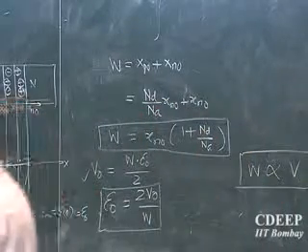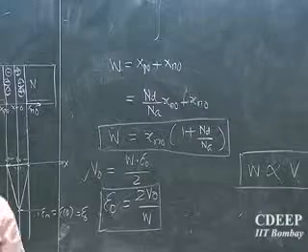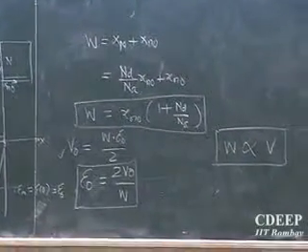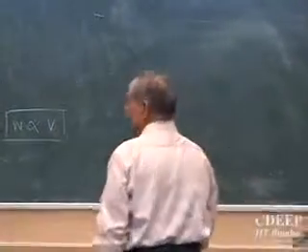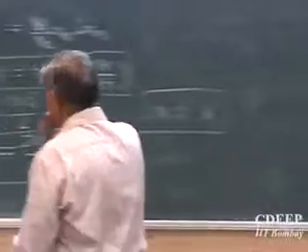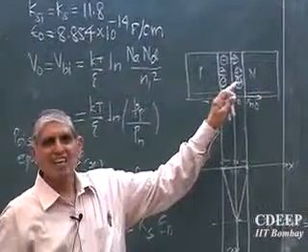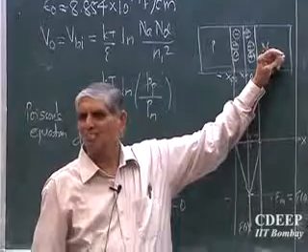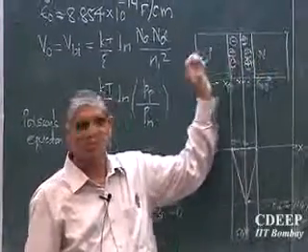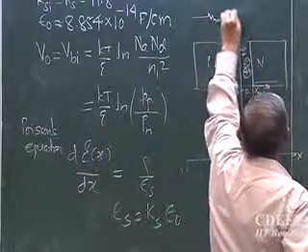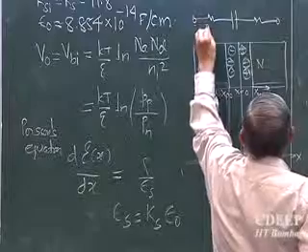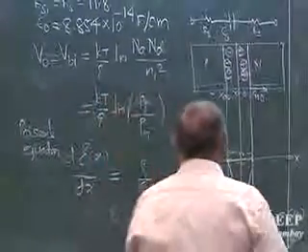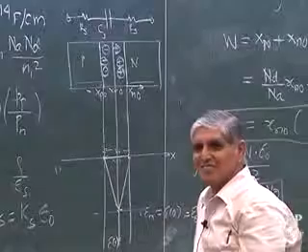Anyway, I would have done it later, but I want to know the relationship of this depletion layer with voltage. If I do that, then I may get what he is asking, because now I see something very interesting. These are ionized acceptors and donors, like an electrolyte. This is neutral, so it has a small resistance, though it cannot be zero. So this is equivalently R series, C junction. There is another resistor here. Can you tell me where is another resistor?